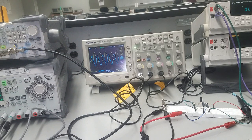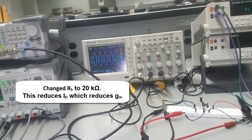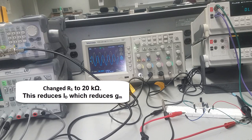So now we made the source resistance close to 20 kilo ohm. You can see that the gain dropped dramatically, to roughly 35 volts per volt. We need a gain of 50. So by making RS bigger, the current dropped, and because the current dropped, GM dropped, and that made the gain lower.